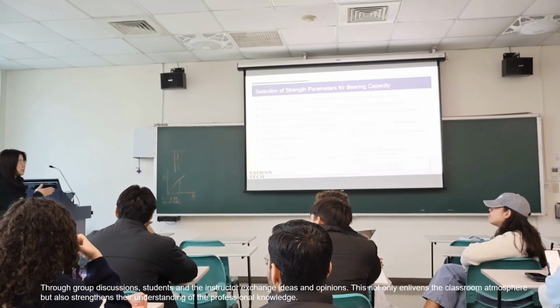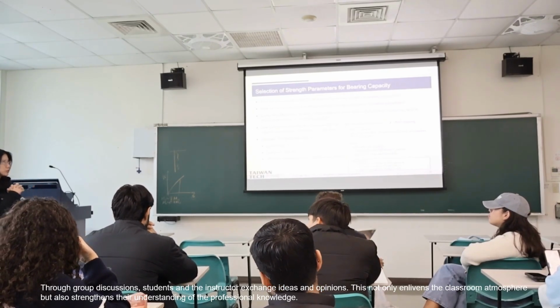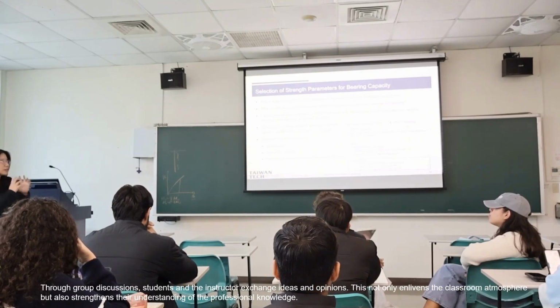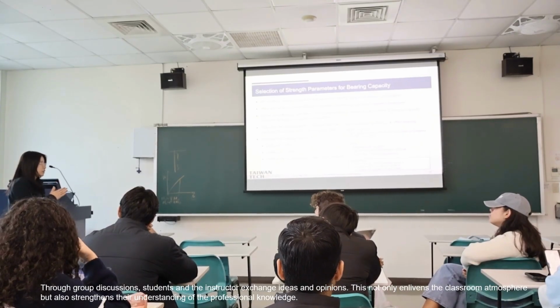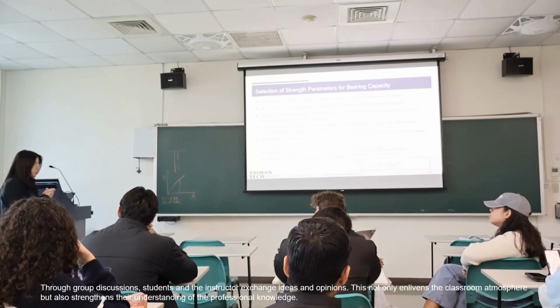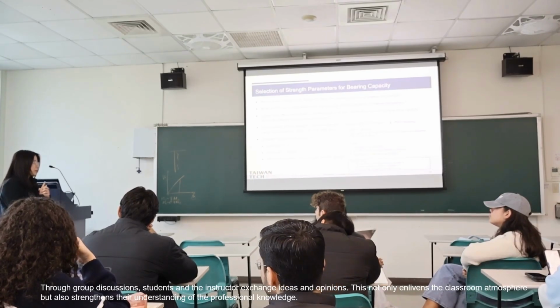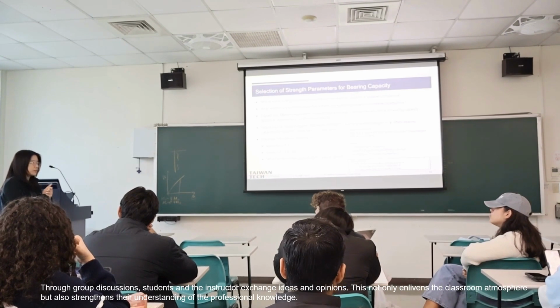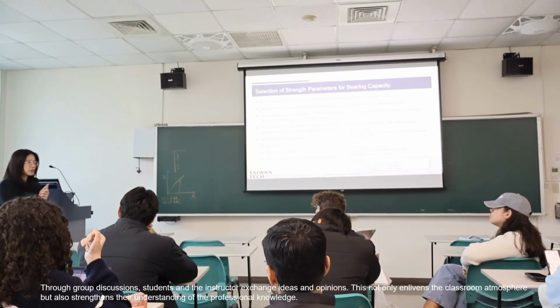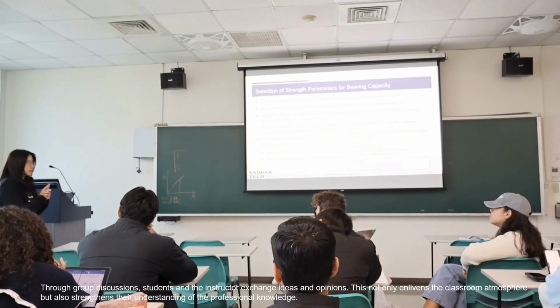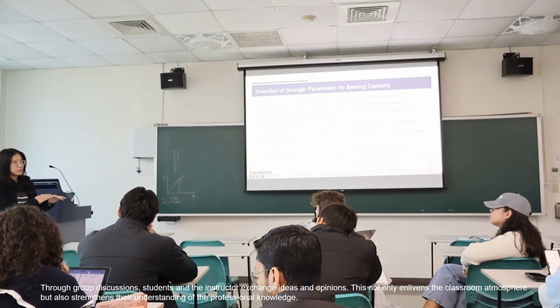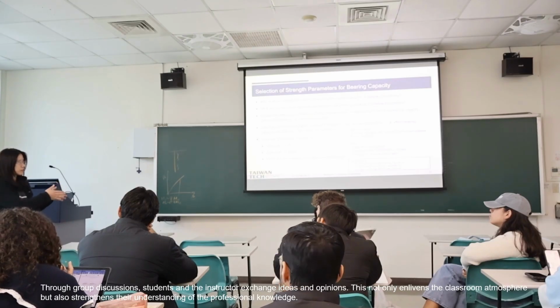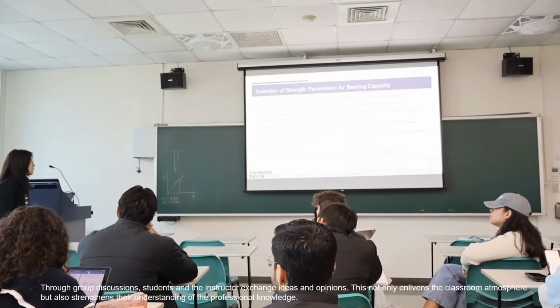But this is just for bearing capacity. The most important other factor we still have to consider is the settlement. In our first week, I mentioned we also have to check the settlements. If it's a huge settlement, then even though we can have enough bearing capacity, if the settlement is too large, the controlling factor is the settlement.